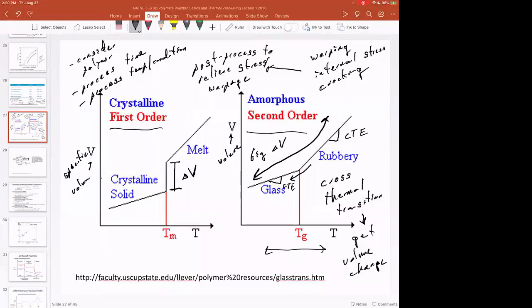But if you can really control the temperature, if you can keep it in a small range, you can still get your glass to rubbery transition, which is what you need, but perhaps you're not traversing as high of a temperature, or you're keeping the part more isothermal. And of course, the more isothermal something is, or the more something stays at the same temperature, the less internal stress you're going to have, because if the temperature is constant, the volume is going to be constant.